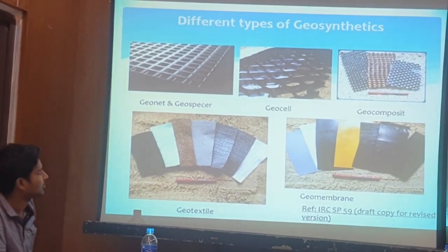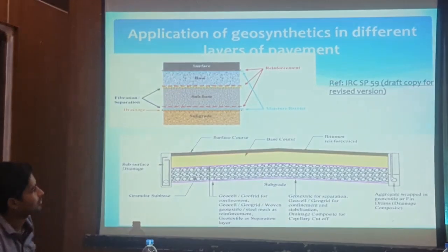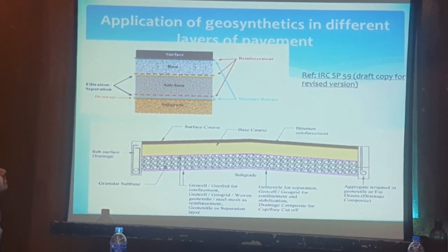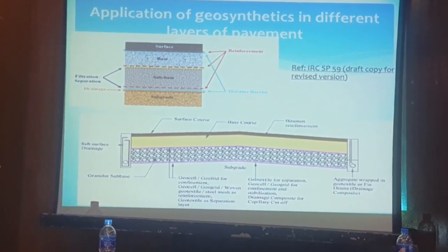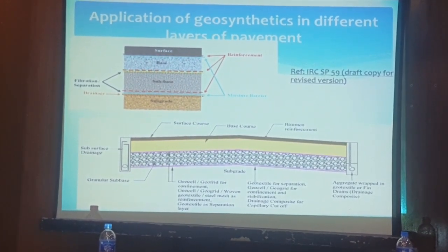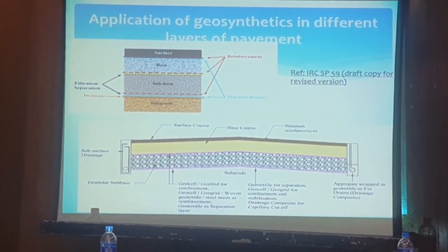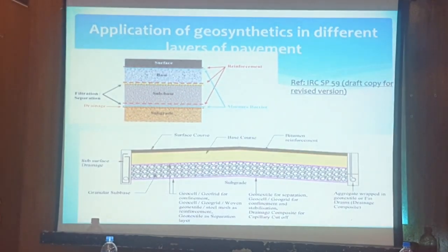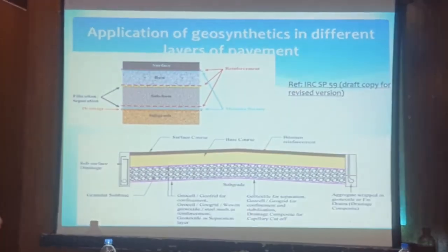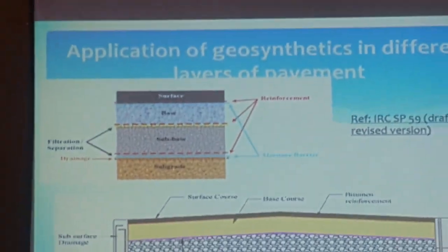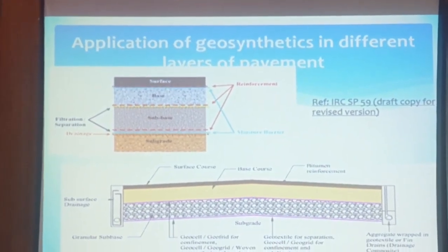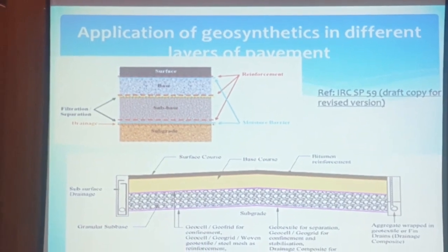The application of geosynthetics in pavements is there. It can be used as asphalt reinforcement, or it can be used in the non-bituminous different layers also. In IRC 37 it is there in the form of some modulus modifying factor, 8.2. Okay, like that.